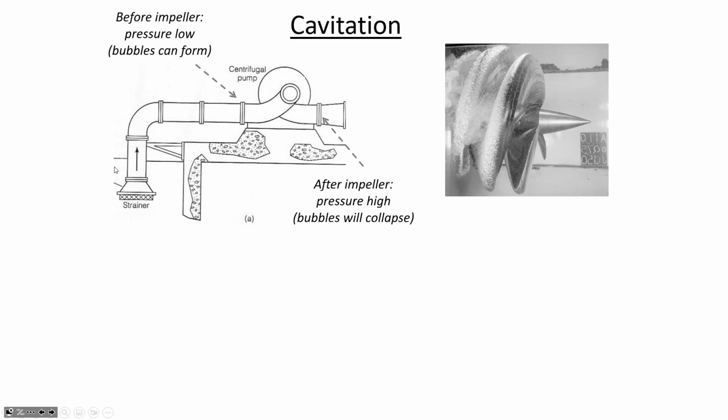Now pressure is increasing when you go down. Then when you go into the pipe, the pressure is decreasing in the direction of flow. So the pressure is getting lower and lower and lower. And so what potentially can happen is that if this suction side pipe is long enough, or if there's a big vertical deflection, like if the water level is really low and you're having to lift the water before it goes into the pump, then you can have a location of really low pressure where cavitation could form on the